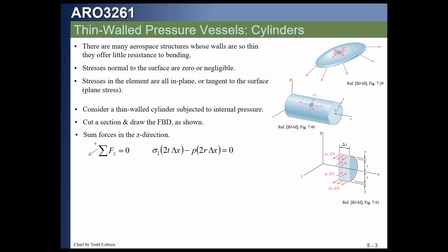We're also going to note that if the wall is thin, like super thin, the thinner that wall gets, the closer r inner is to r outer. So often these equations will be simplified. They'll just be identified as r, and you're wondering, is that the inner radius or the outer radius or the midplane radius? We're just saying r is r because there's not a whole lot of difference if your r is large and your thickness is t. You got that? But for a strictly correct equation, for this particular figure with internal pressure, that would be the inner radius.